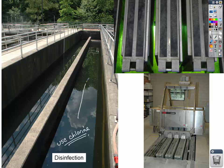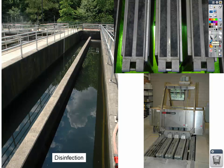So you'll see this tank, the water on its journey has to make a left-hand turn, another left-hand turn. It's going to take a long time for this water to get out so that the chlorine has a chance to degas before it goes back into the environment. Some newer technologies, up here in the top right, you see UV radiation. They're using ultraviolet radiation to clear the water of any remaining bacteria or pathogens. That's very costly, but it's a solution to not use chlorine. So these are the methods we use to disinfect, the last step of the wastewater treatment.